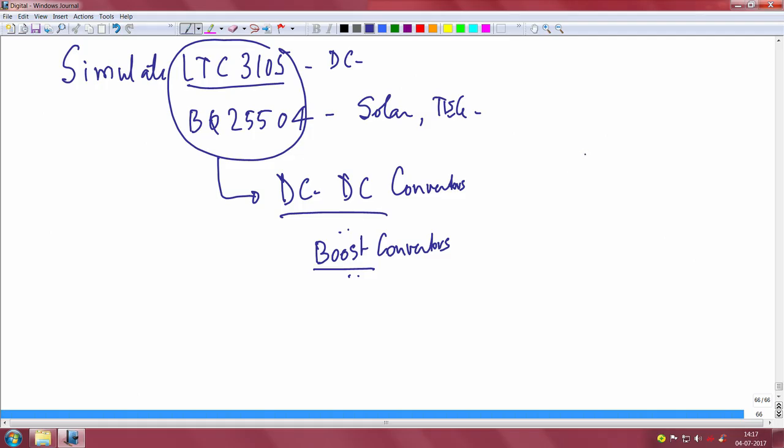There is a PWM generator, and the PWM output drives the series pass element, and the duty cycle of the PWM decides the output voltage. Input to output is determined by the PWM signal. All this we spoke about. What is special about this boost converter with respect to energy harvesting is the question.